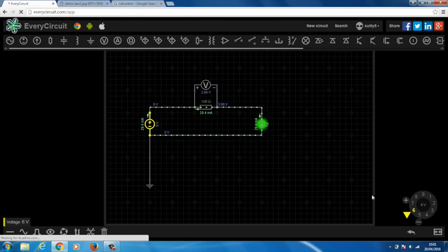And if I decrease the voltage in the circuit to 4 volts, we can see the current in the circuit has also decreased. So we're now down to 10.9 milliamps, and that LED is barely lit. I'm going to set this back to 5 volts, and now we're going to adjust the resistor value while keeping the voltage constant, or keeping the voltage the same.